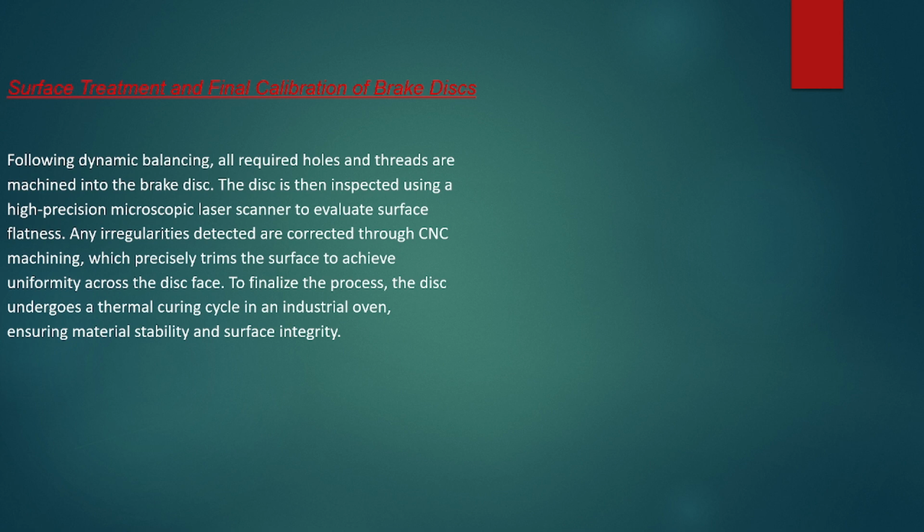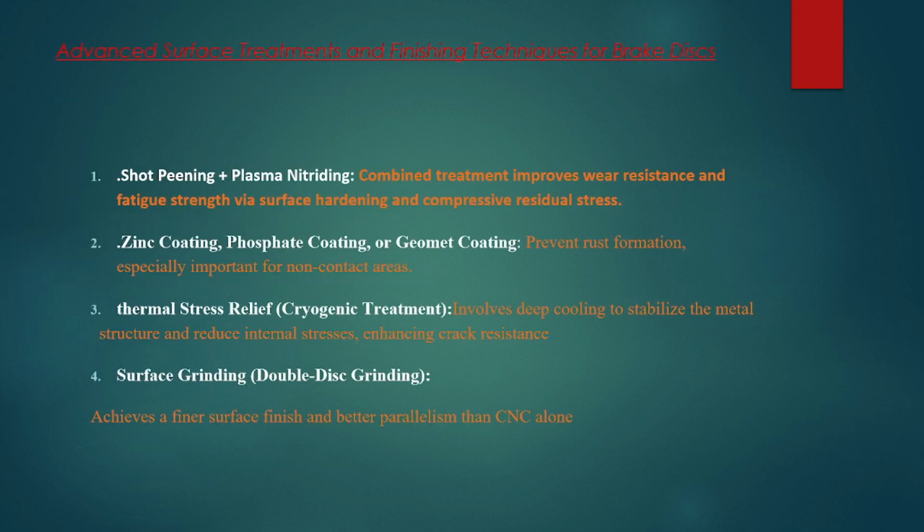Now let's go into deeper information on the surface treatment. Advanced surface treatments and finishing techniques for brake discs. We have shot peening plus plasma nitriding. The combined treatment improves wear resistance and fatigue strength via surface hardening and compressive residual stress.